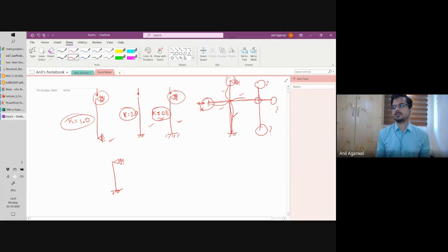What is happening at all these locations, whether it is continuing again as a column or a beam, or it is getting fixed here, what kind of boundary condition you have. So basically you have some kind of a rotational fixity present here. This is a rotational spring. It offers resistance against rotation. Okay. Now the stability behavior of this kind of a column will become more complex, and the stiffness of this spring,